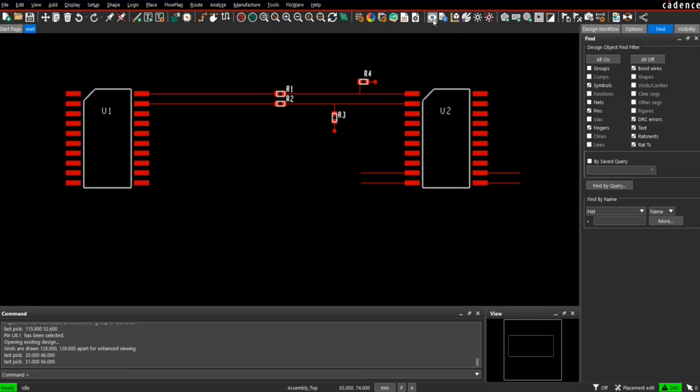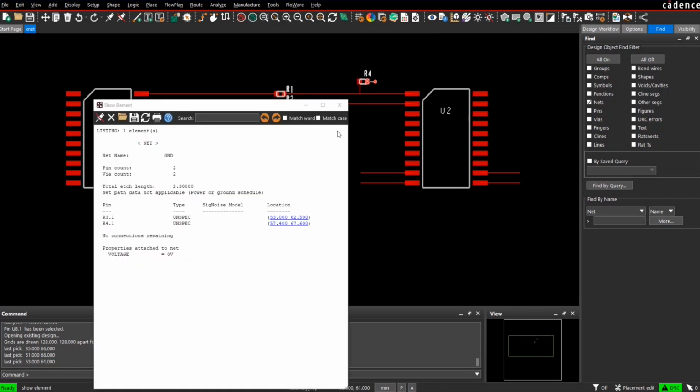And what we also see in addition here, there's a second resistor on both of these nets, connecting them to ground. So pulling up resistors, for example. But obviously ground is not included in one of these XNets. And this is exactly controlled by this voltage property. So as soon as a net is a power net with a voltage property, the XNet generation is stopped at this component.